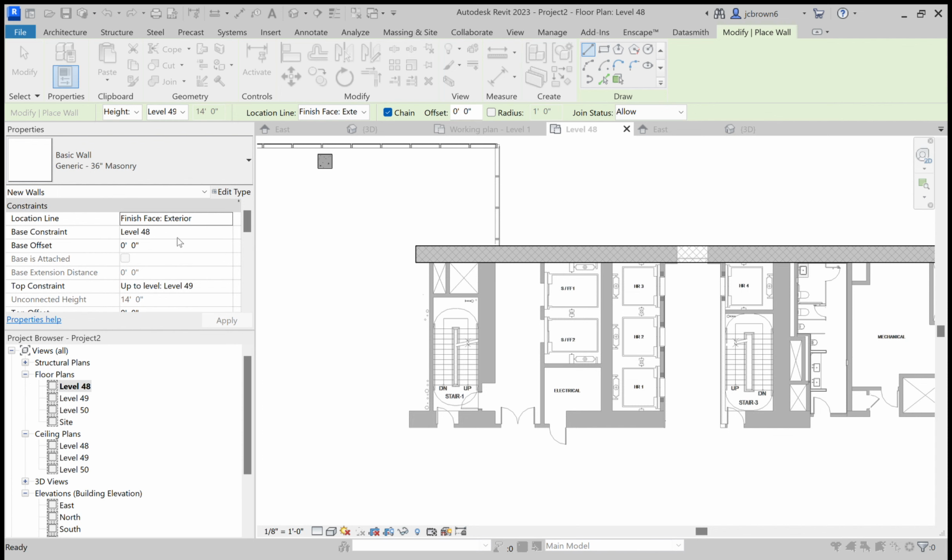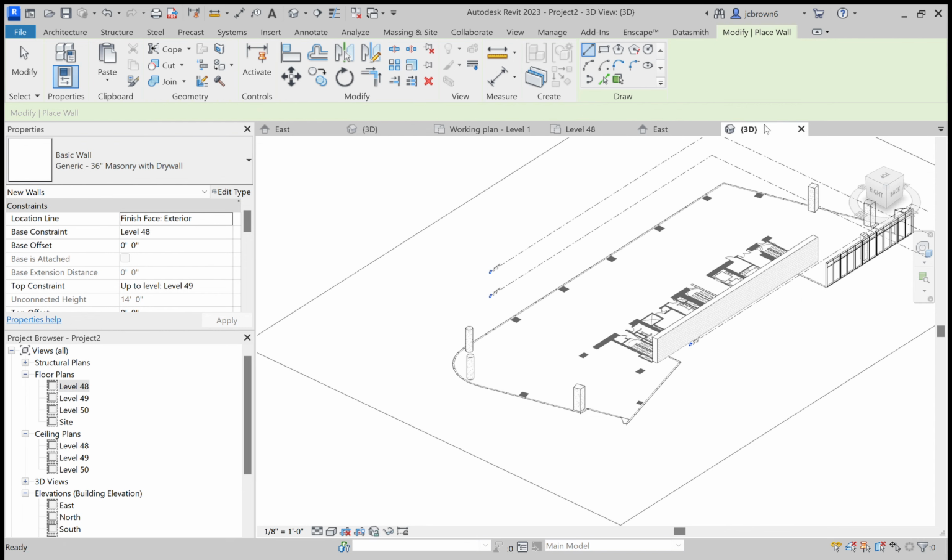So if you notice in this wall assembly, the concrete is the structure. That's the core of that particular wall frame. But we're going to add a finish, which is drywall. So we'll change this to finish, and we'll change the material to drywall. We'll hit OK, and we'll use a 1/2-inch board. So we'll change that to 1/2 inch. And notice at the top it says exterior side, and this says interior side. So we know it's on the right side. We hit OK, hit OK.